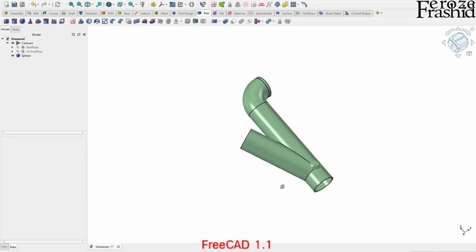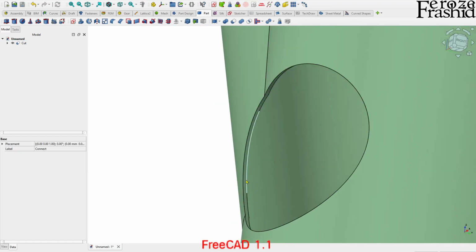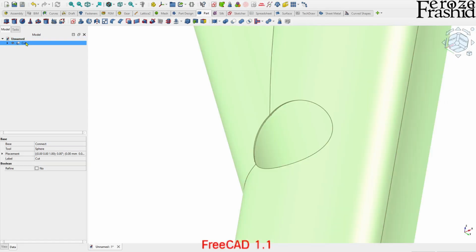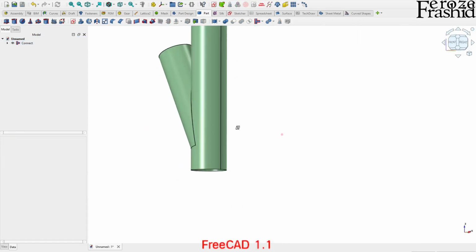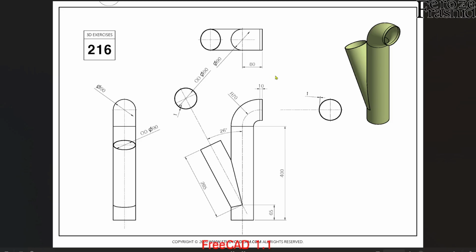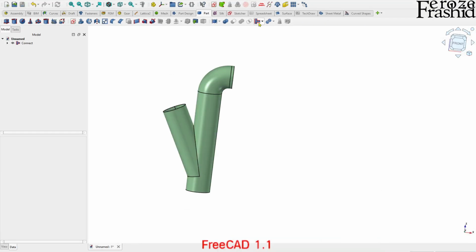All right, and now let's make a cut. So take this connect and take this sphere as the second choice and make a cut. You can see that it's cutting very nicely, which means that this object is a proper solid. It will do Boolean operations very nicely. Alright, my friends, that is the little experience we wanted to have on part design. But when building a pipe, sometimes it is easier to join them together using a part workbench tool named connect object. If it failed, we would have a different approach. But for now, that's what we wanted to show you on this video.